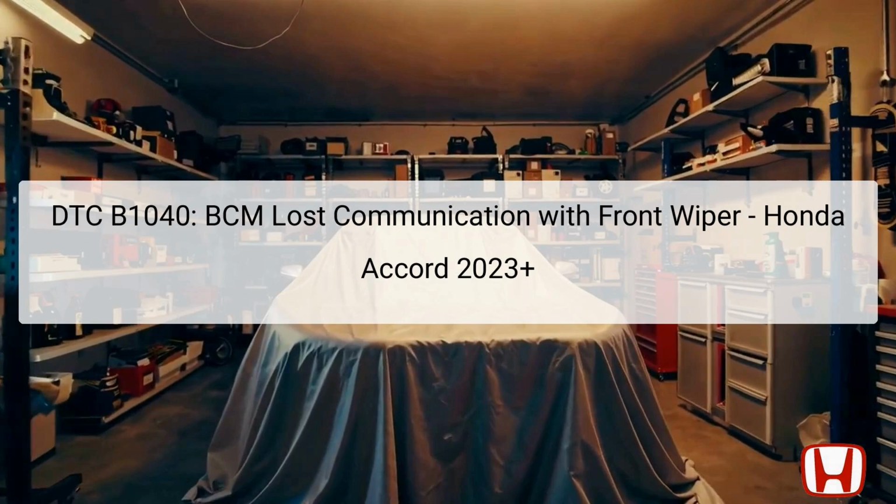The DTC code B1040 indicates that the body control module, BCM, has lost communication with the front wiper control unit or motor. This diagnostic trouble code is crucial because it affects the operation of the windshield wipers, which are essential for visibility during adverse weather conditions.